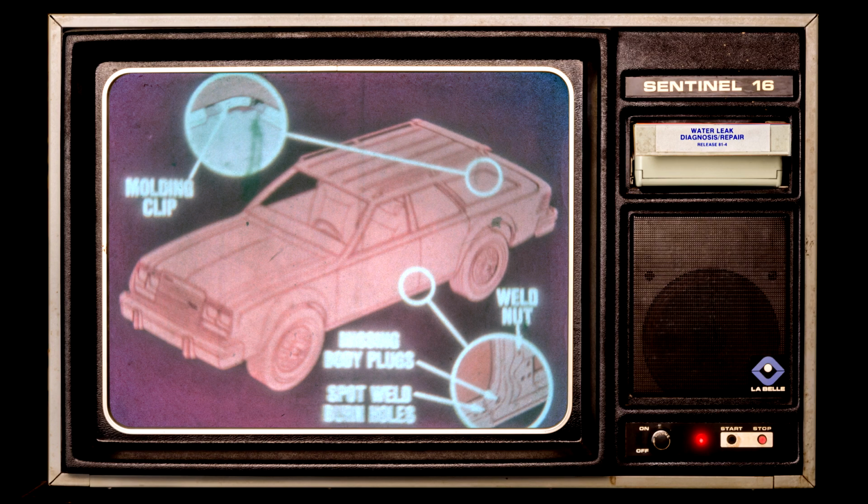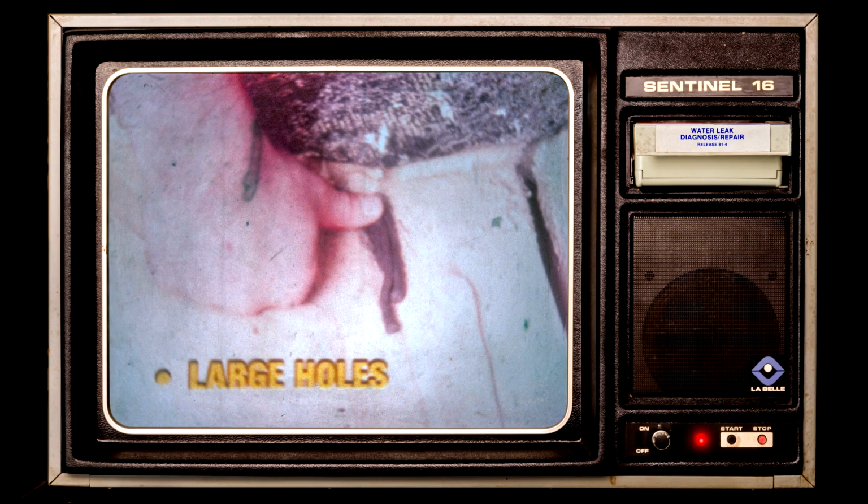All of these leaks can be sealed with the same types of sealants: holes at weld nuts, screw holes or molding clips, missing body plugs, and spot weld burn holes. The recommended sealant varies with the size of the hole. Large holes can be filled with another product called strip caulk.